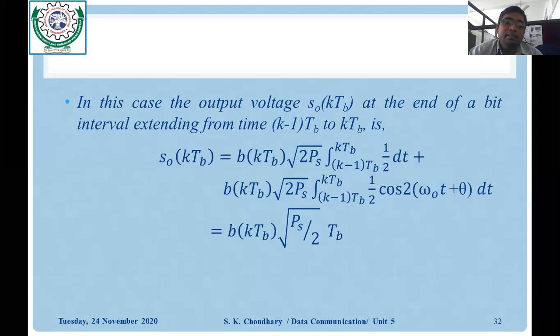When you integrate this, you will find that this sinusoidal term becomes 0 for the complete cycle of the bit duration, since the sinusoid spans a whole number of cycles. So only the first term is used here to produce the original data format.